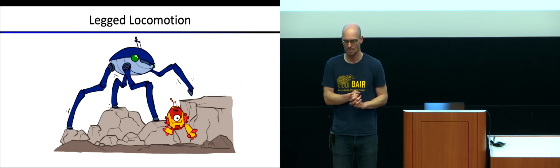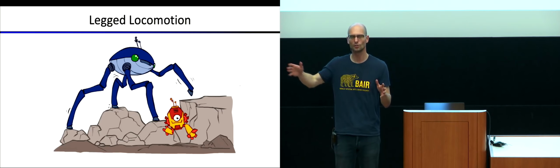We then, to learn a good controller in the simulator, used something called iterative LQR. What iterative LQR does is essentially look at a trajectory and try to find a linear feedback controller at each time slice. So the parameterization of the controller is a separate linear feedback controller for each time slice.